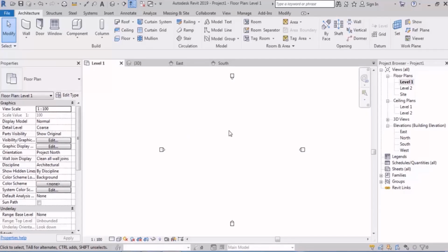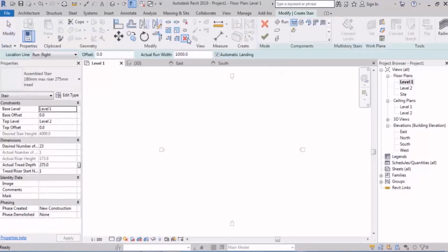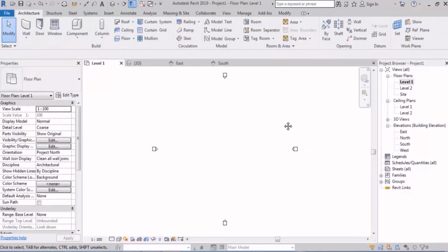Now a point. While you're editing your stair, at every level, each level, you need to click on that check to make sure things you have done so far have been accepted by Revit or not. Actually, this is very good for you because you can understand where you have made a mistake. If you do it immediately after each other, you can understand that, yeah, it has been a couple of levels back that I have made a mistake. You need to understand where the mistake is.